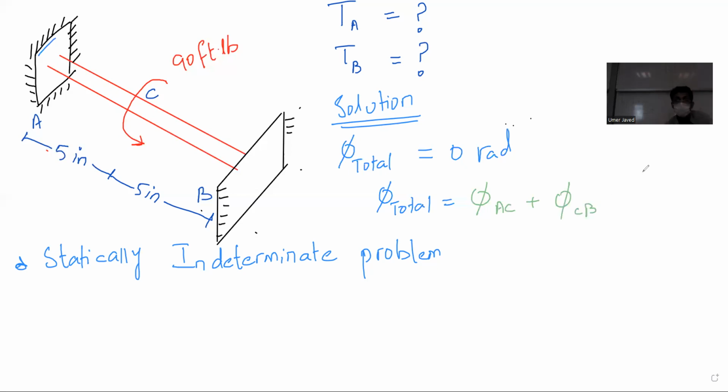So why it is zero? Yeah, because this is inside this and this fellow is inside this. So when you are putting a torque, the total twist will be zero. There will be no change of angle. If I have firmly put some structure like this, and I'm putting a torque, what will be the total twist end to end?